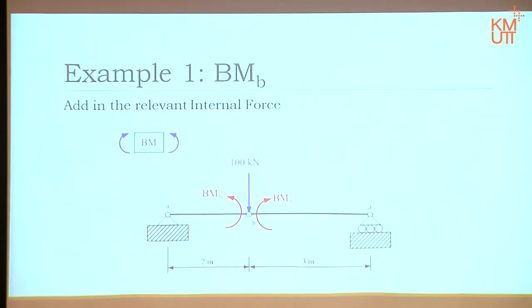If point B moves up, point D cannot go up. Point D has to stay with the support. Then BD rotates at the same time anyway. Okay? So once I do it, it will be in this one. But this one, I rotate it back down. Okay, meaning I rotate AB clockwise, meaning point B will come down. Okay.